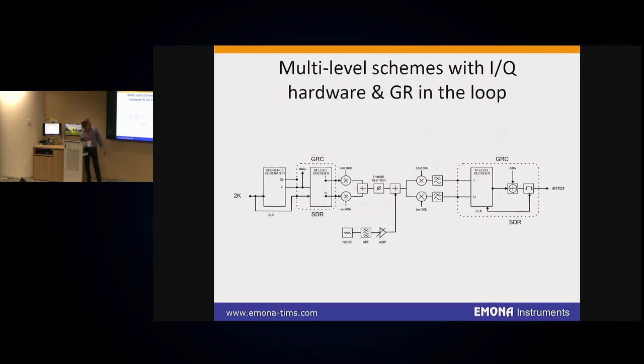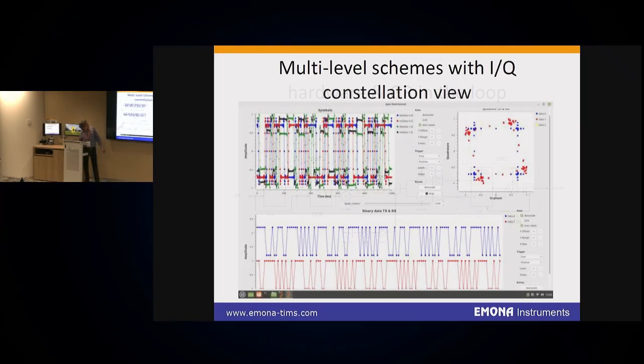So here we can see a complete transmission system where we have an IQ modulator at the transmitter and an IQ demodulator at the receiver. An example of IQ modulation is with multi-level schemes where the I and Q signals respectively modulate in the horizontal and vertical axis, otherwise known as the in-phase and the quadrature axis relating to the cosine and the sine RF carrier.